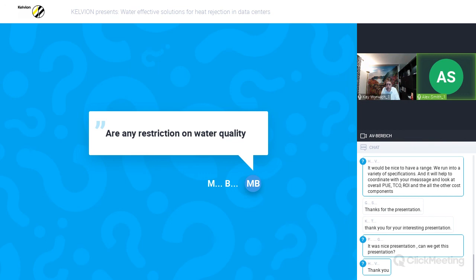You can also compromise on water quality, but at the same time, the better the quality of the water, the better. We also have a strainer in the system as well. The system itself will often have one, not just ours, but other systems too. But that will only take out large particulates, so any debris that's in the water. The actual quality of the water itself, the scale and the mineral deposits, has to be controlled.